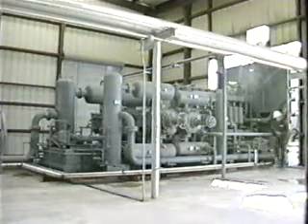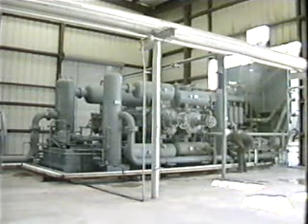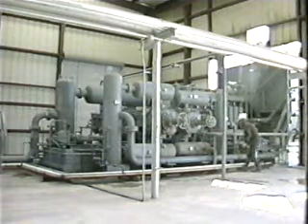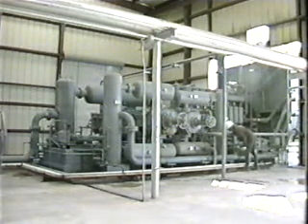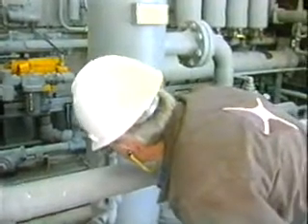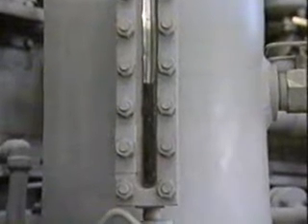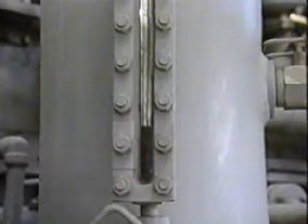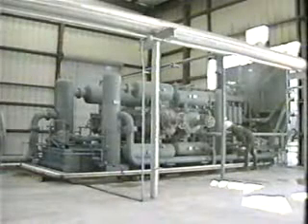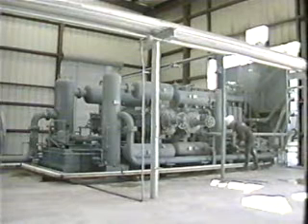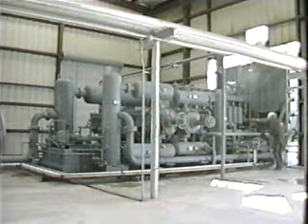Starting with the scrubber, check and record liquid levels and supply pressure. Then look over the fittings and seals. Tighten them if necessary. Adjust the pressure regulator as needed. Manually trip the liquid level controller while observing the function indicator and dump valve response. The valve should respond smoothly, and there should be a decreasing level in the sight glass. If the automatic dump valve is not working, manually dump the liquid and report the unit for repair.